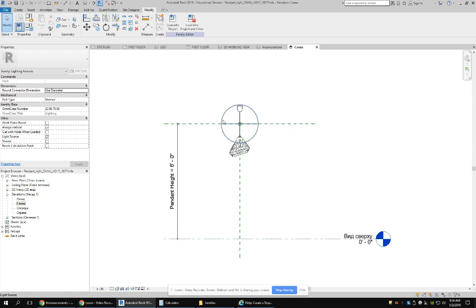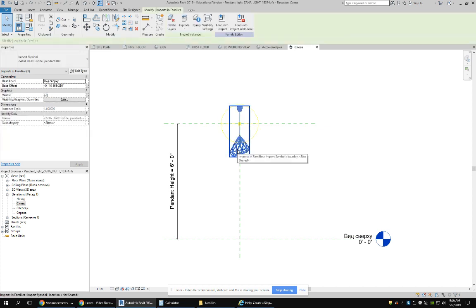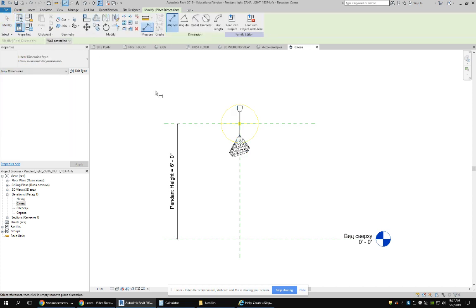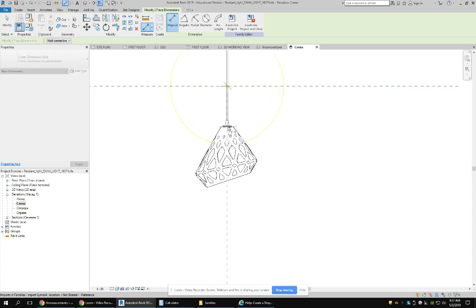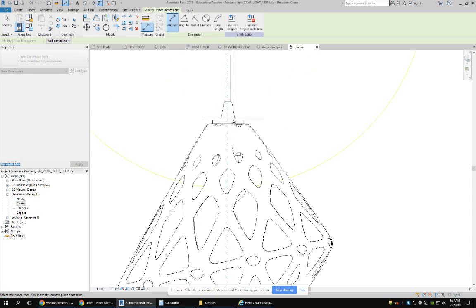And the plot thickens. So this tells us that the light source itself is attached to this pendant height, but the object, the nested object, it looks like, is not. So I need to find out how to attach that to that light source. So let's see if we can lock it in. So I'm going to annotate a line dimension from the reference plane. Let's go to like this bottom edge of the, let me see if it will let me pick that line.